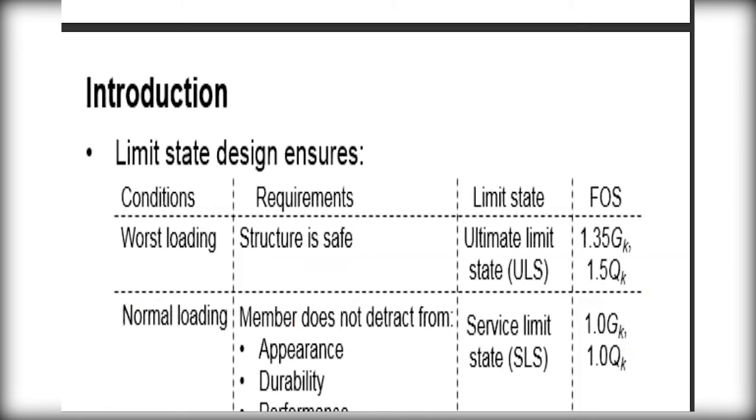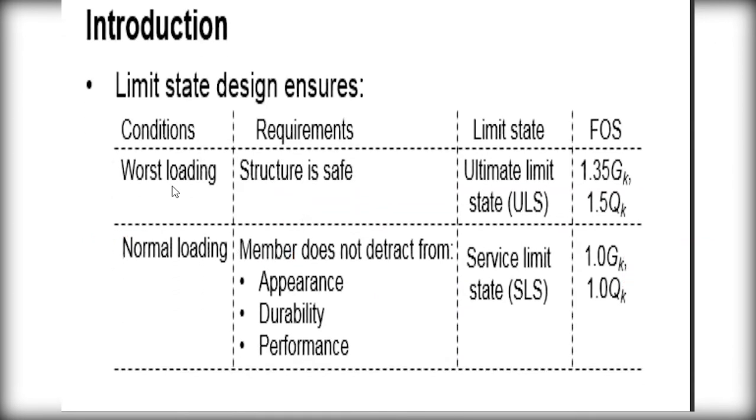And this should be very understandable because it is usable in designing in several cases. So whether we design it as ultimate limit state or serviceability limit state, for the ultimate limit state it is 1.35 in Euro and 1.4 for the BS. And here is 1.5 for Euro and 1.6 for BS.